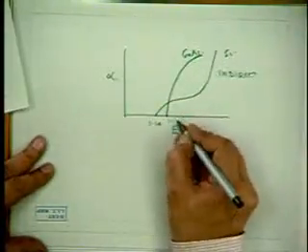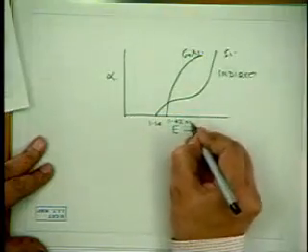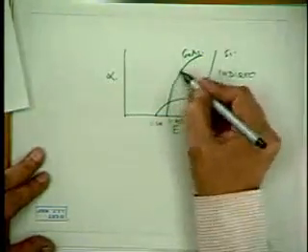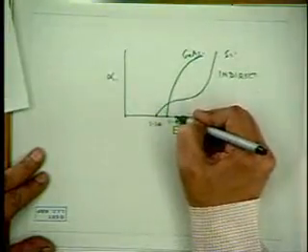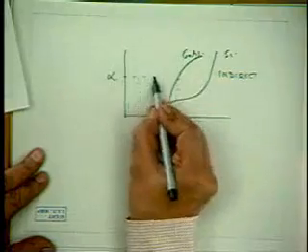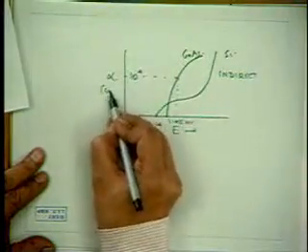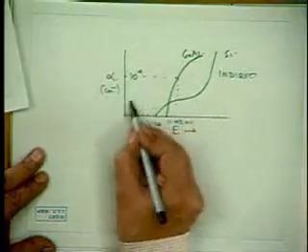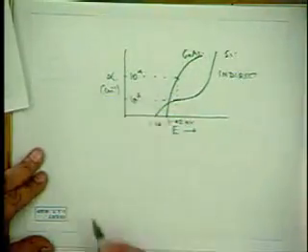This is at the edge of 1.42 eV, and we have a very rapid increase. So at a slightly higher energy of about 1.5, the absorption coefficient of gallium arsenide could be something like 10 to the power 4, whereas the absorption coefficient of silicon would be of the order of 10 to the power 2.